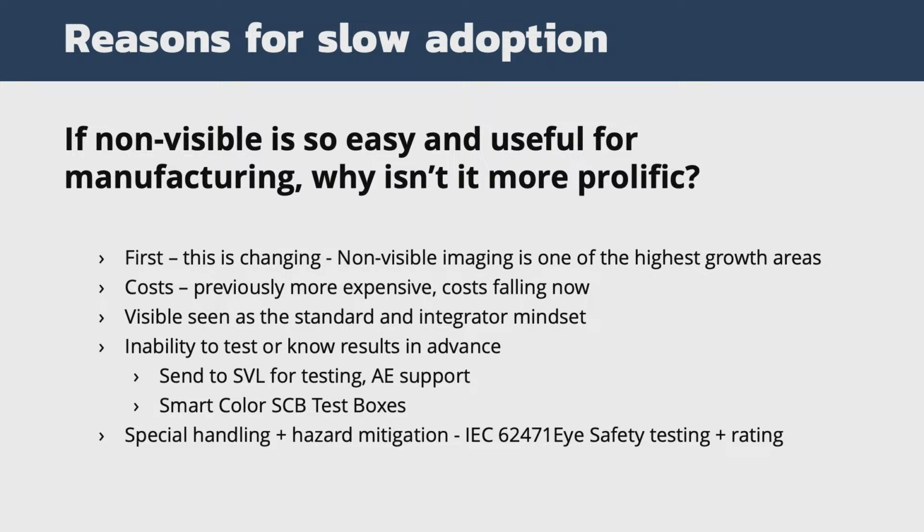We have a standard IEC 62471 eye safety rating on all of our products. You can tell from that the level and what you may need to do to protect. Largely, you just don't want people at very close distances looking directly into the light. If you're taking any effort to shield the light or keep people from directly looking into it, you're probably safe in most cases. We can't tell you definitively.